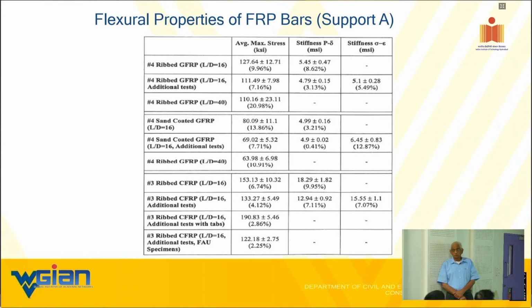under 3-point bending, you know what you're going to get? You are going to get second-order nonlinear effects. So we never want to get there. This is the P delta effect, we call it. I don't know what you call it. It's a second-order effect if L over D goes beyond 40, 38, 39, 40, in that range.